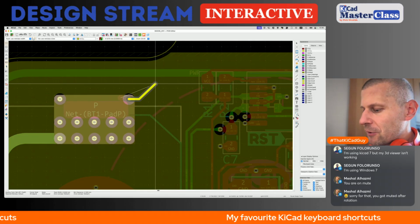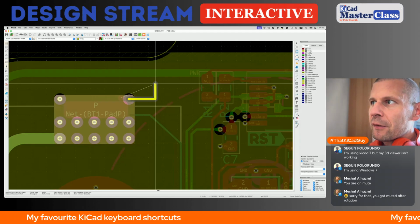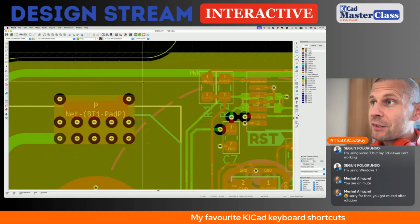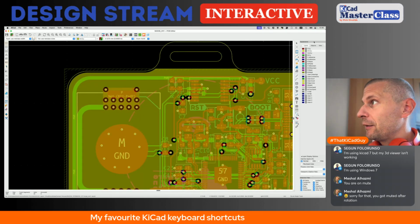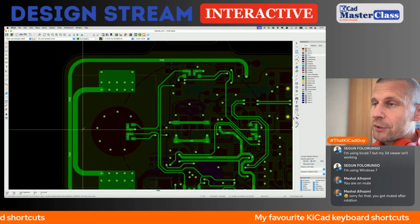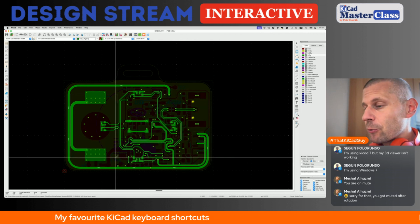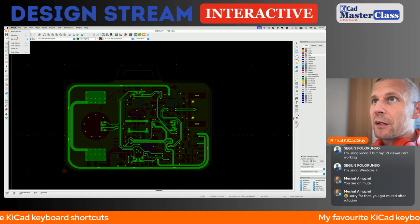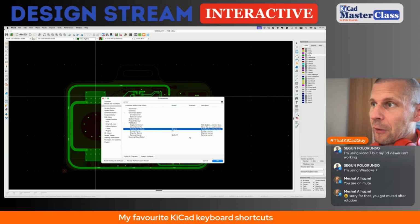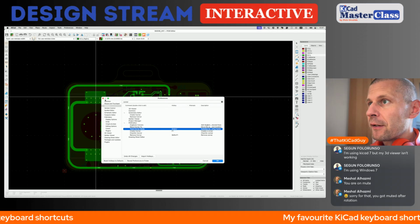On my Mac, when I press command and slash, I'm changing between 45 degrees, rounded, 90 degree rounded, and back to 45 degree. So sometimes, for instance, here by accident, you can see in the bottom layer, I used rounded corners for these two or maybe three traces. So corner style, in my case, command slash, and we can check how the function is called. It's called track corner mode.